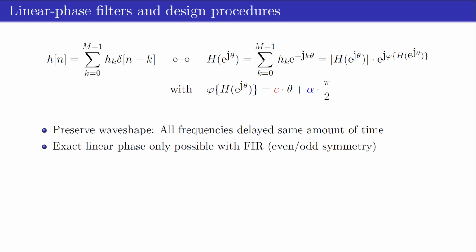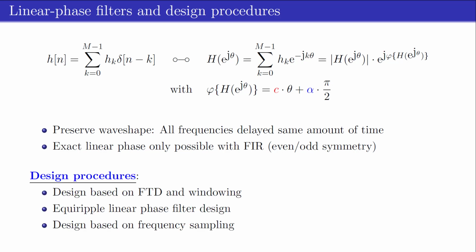Because FIR filters are generally designed to have linear phase, we consider the following three design procedures: based on the Fourier transform for discrete-time signals and windowing, based on equiripple filter design, and finally based on frequency sampling.